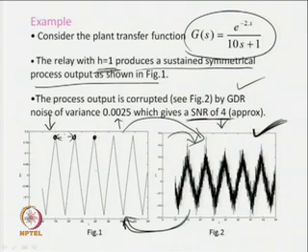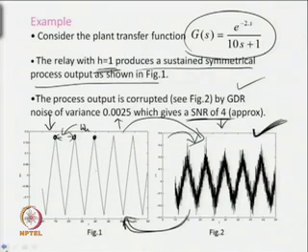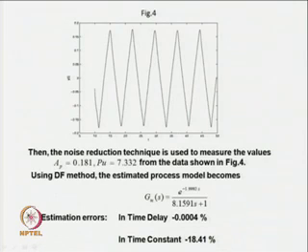Okay. And from the period you can get correct information about the ultimate frequency. Okay. Now, how to find the magnitude? Now, once I have located where the peaks remain, suppose at this time the peak remains, then I will take the average of this signal around that and I will get correct information about the peak amplitude. Thus, it is possible to obtain or retrieve the signal from the corrupted or noisy signal.